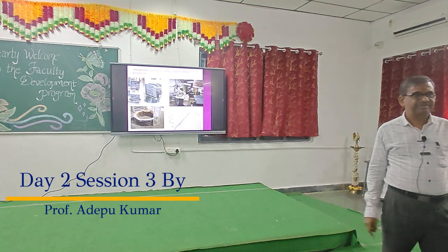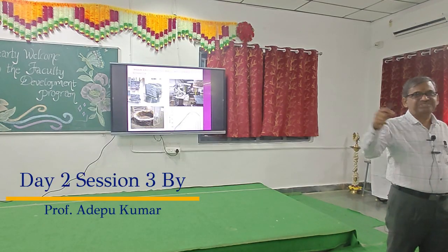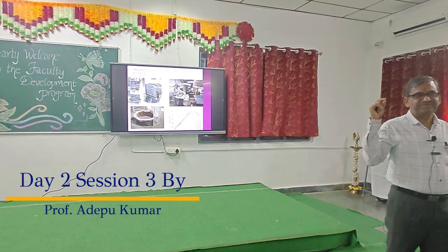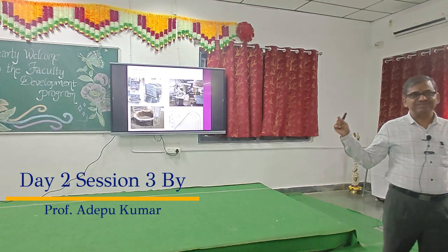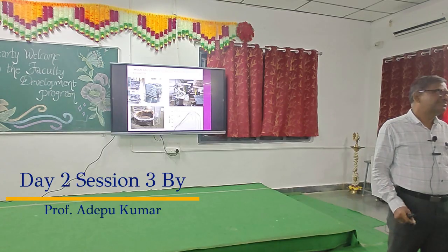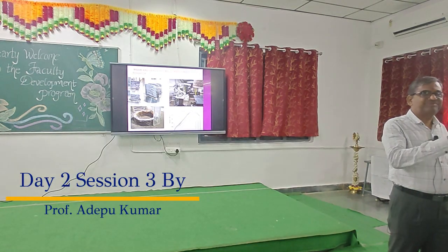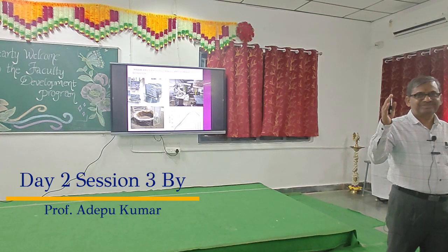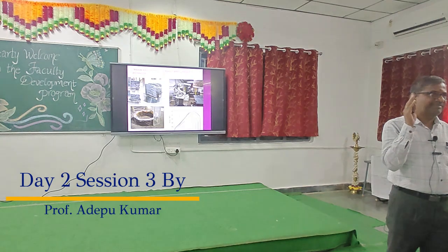the material. For example, I want to weld, let us say, a 1 mm thickness sheet. If I give a job to you, 1 mm thickness and 6 mm thickness, the 6 mm thickness fellow is very happy compared to the 1 mm thickness fellow, because there will be less distortion. In 1 mm you have a large distortion because you are supplying the heat input continuously.